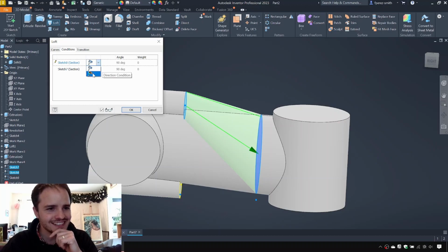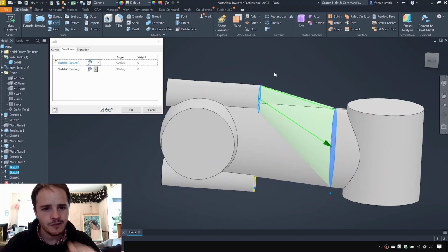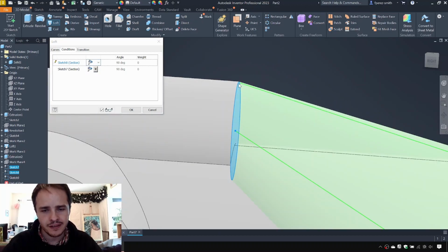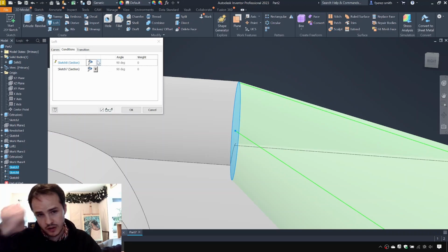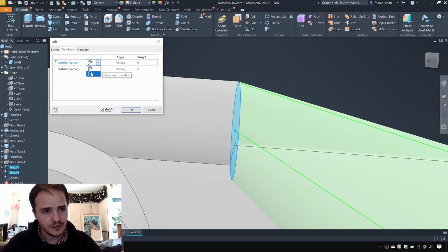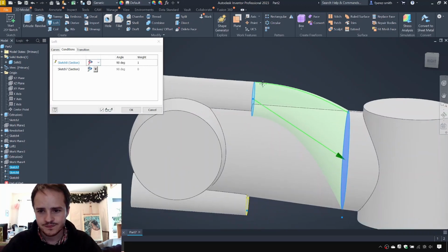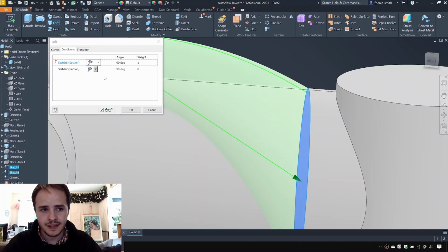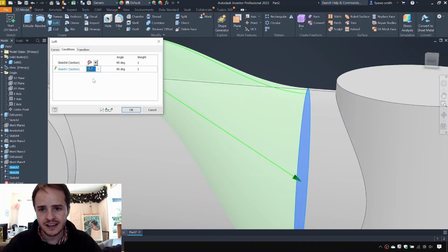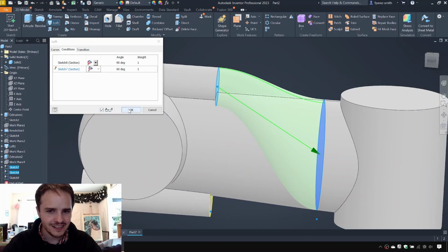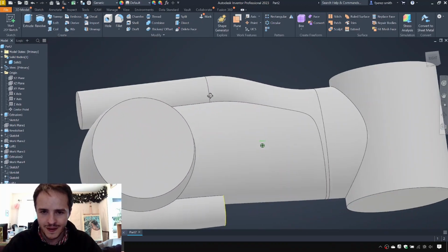We're going to make these tangential by putting a directional condition in. So if you see, do you see how that line comes from that sketch? By default, it's just going straight from one point to another, but if you add this in, it will make it nice and tangential. And you can do the same for the bottom here. You can say it's straight or it's nice and tangential. Lovely. It looks like a manifold for a car.